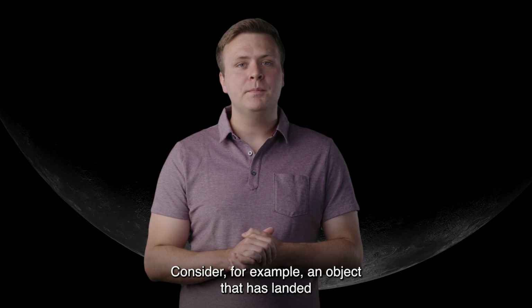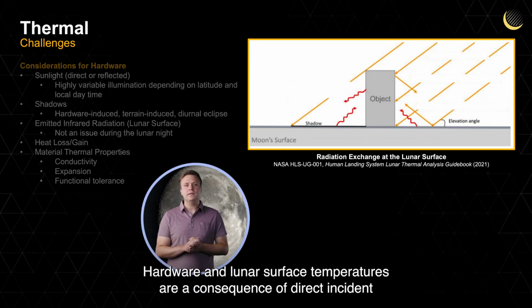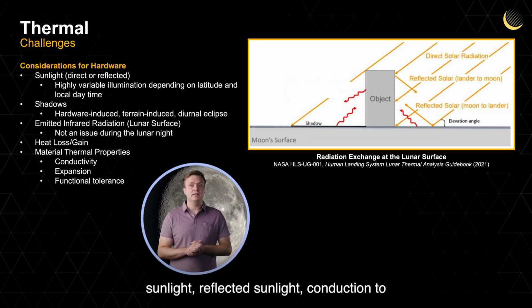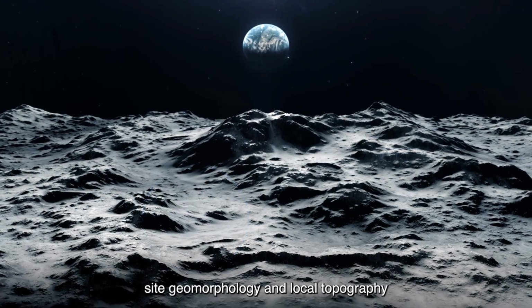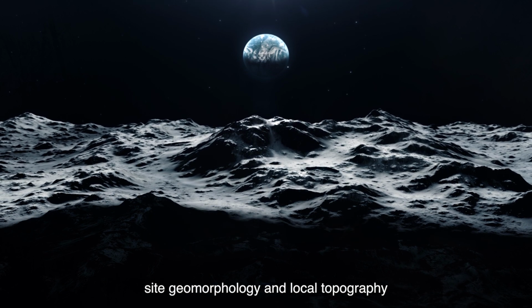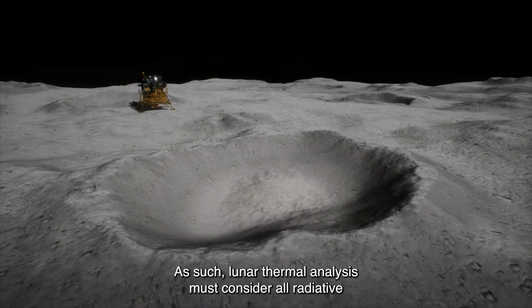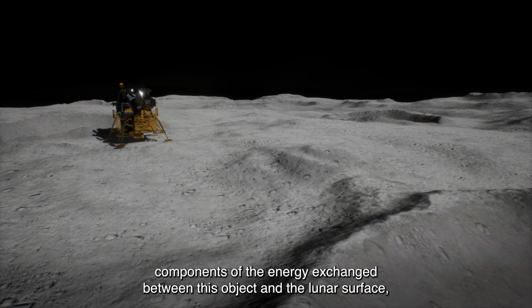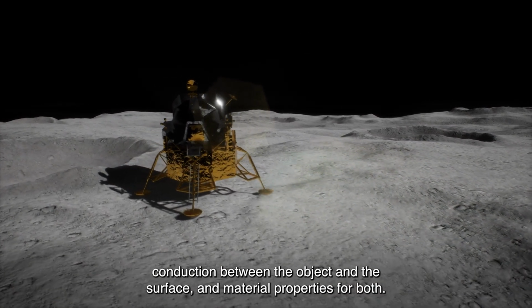Consider, for example, an object that has landed on the lunar surface. As shown in the image on the right, hardware and lunar surface temperatures are a consequence of direct incident sunlight, reflected sunlight, conduction to and from the object, subsurface heat flow, and view factors to space. Time of day, site geomorphology, and local topography also play a role in establishing the heat balance for a given system. As such, lunar thermal analysis must consider all radiative components of the energy exchanged between this object and the lunar surface, conduction between the object and the surface, and material properties for both.